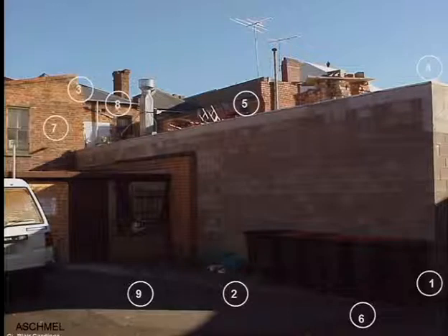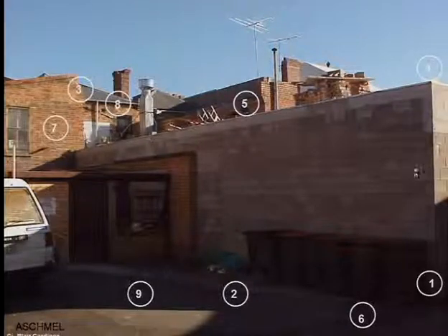Okay? Can the building take a loading? Can it take additional load, which means I need to get a geotechnical report? Where is the site boundary? Because if you look here, see this comes into the side of the neighbour's wall, but the neighbour's wall extends. So where is the property boundary? Where are the services? How do I get the existing water supply and storm water out back here? Because at the present time, it actually runs over this area.